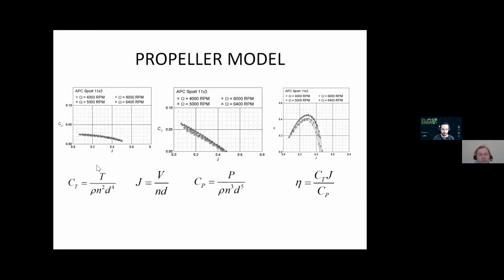So, what was the idea and the motivation? As we know, the main phase for the copter is hovering, but from time to time it must lift to some altitude, and maybe for some reasons this altitude must be rather high, and for this case we need to choose the flight mode to, for example, minimize the energy consumption.